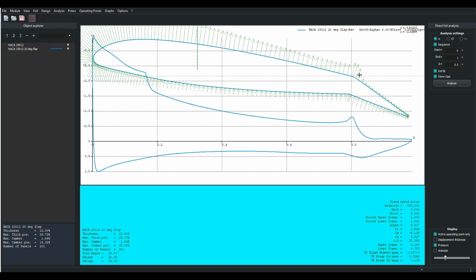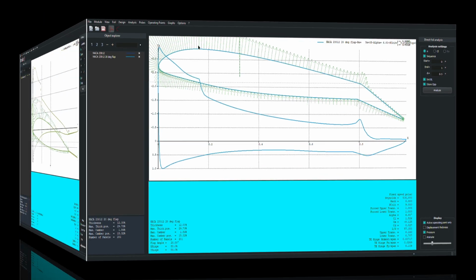It doesn't generate as much lift at its leading edge, so you don't get as much nose down pitching moment, but we can make up for that by making the chord of that flap a little bit larger. But it solves the problem in terms of this pressure distribution, creating a wall here. If we don't create this wall and we get a turbulent boundary layer, we'll get through that adverse pressure gradient. We'll get off the trailing edge gracefully without going spanwise. And that's what I'm going to begin to show you in the next segment.